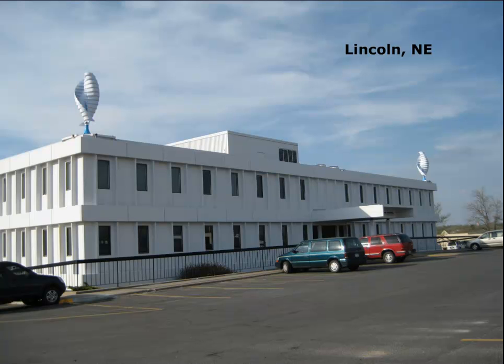Number 1, they're very low to the ground. Number 2, they're on a building, so there are turbulent winds. Number 3, they are of a Savonius design, so they tend to have very low efficiency, so we aren't expecting them to produce a lot of power. And then finally, one of the most important pieces to putting a turbine on a building is that when they spin, they create vibration, and the people inside are annoyed. And so for a period of their life, these turbines were tied down and not even functioning.